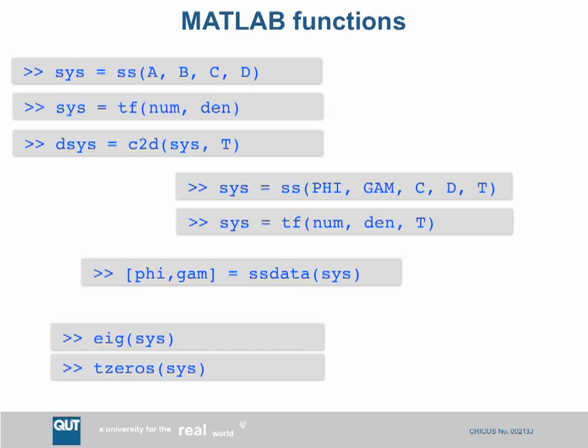What's one of the limitations with a state feedback controller? What do you need in order to compute state feedback? Sense the state. Yeah, you need to sense the state. Now, for some systems, the state is very easy to measure. If you're a vehicle, then the state is probably its position and its velocity, and you can measure that from the odometer and the speedo.